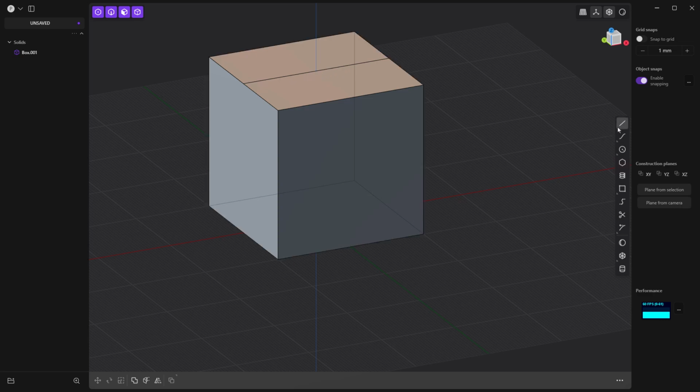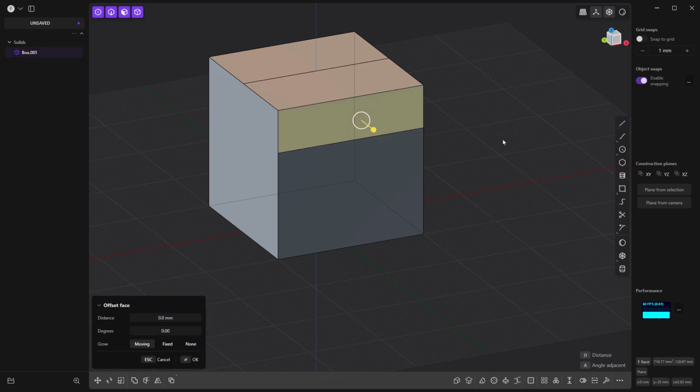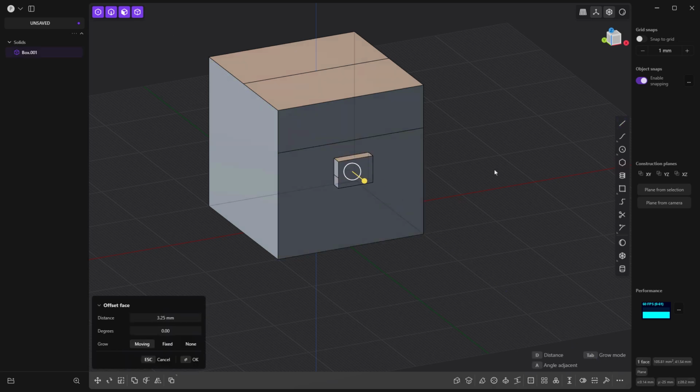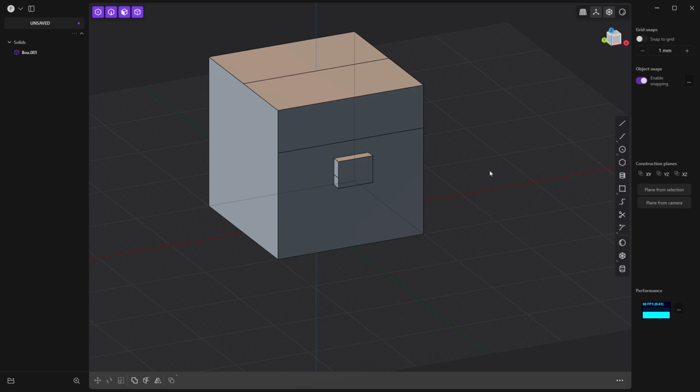So once again, the line tool, K for knife, and then we can start on one edge, go to the other, right click, and now you can see we've divided that object up. So I personally don't think that this is a great option for this type of model, but it is a valid option for all sorts of things. Especially if you want to, say, use the knife tool, and I'm going to hit K one more time, and we're going to sort of draw a section of the block here, and then we could pull this out. Again, 100% valid workflow in a way that we can make a model like this, but again, for our cases, I don't think it's the best option.